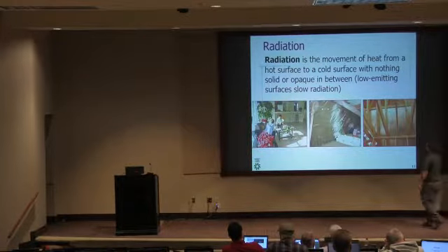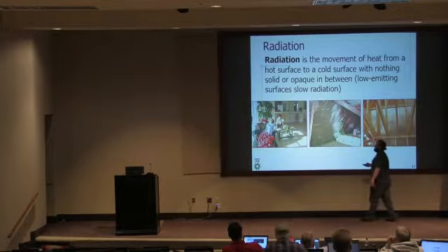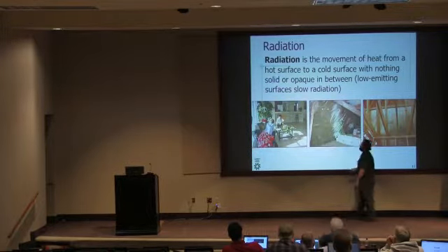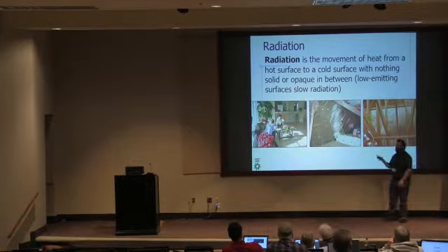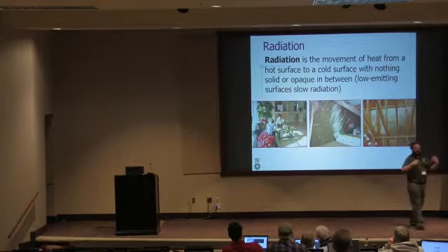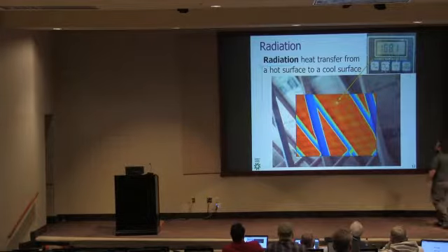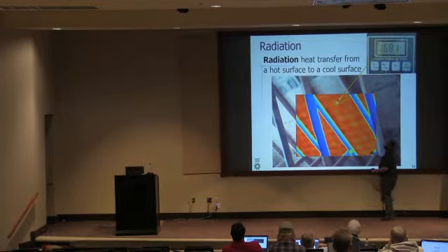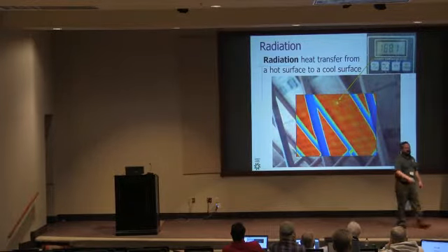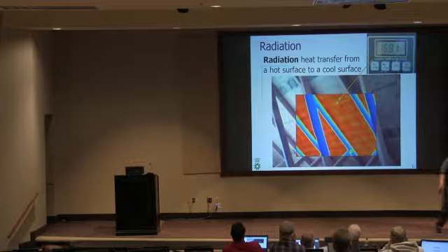And so our houses, when they get hit by the sun, either allow heat gain in through their windows or absorb heat gain in through their roofs, through their attics, that's taken on load that has to be rejected by the mechanical HVAC system. We're looking here at an infrared image of a roof deck. 168 degrees surface temperature on that roof deck. That's hot. You can't really put your hand on 168 degrees. You think of about 165, you'll pull your hand back immediately when you touch it. So those roof decks are basically scorching hot.